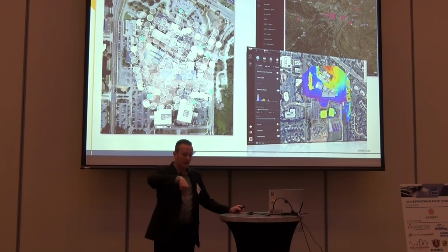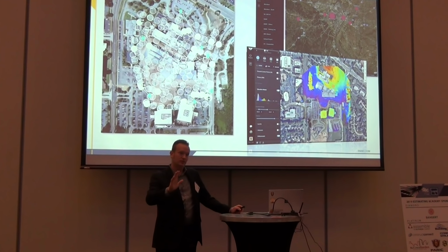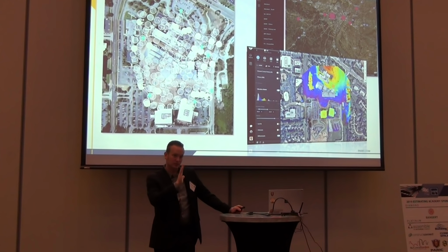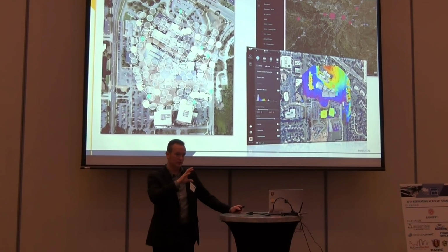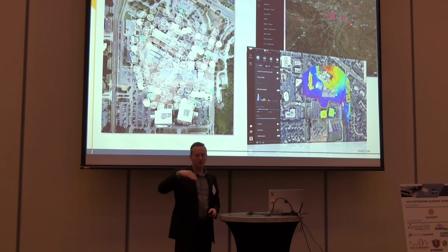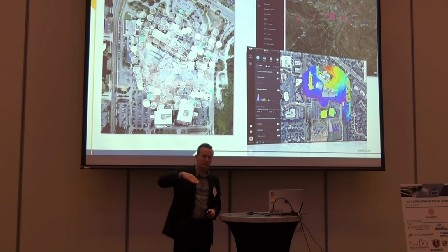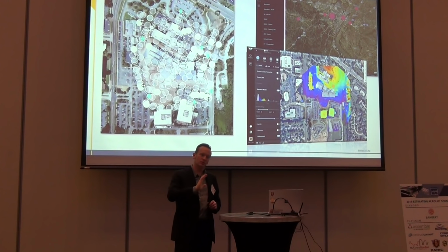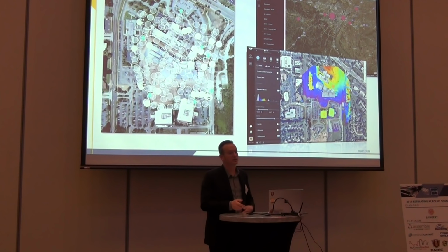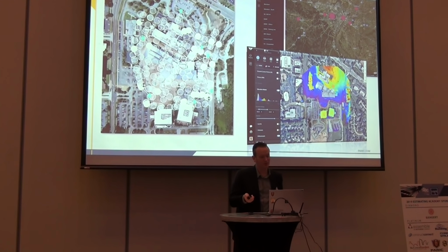If you want to know more about the face of a building, then you'll do what we call a crosshatch scan, but it's not oblique anymore. Depending on what you're trying to scan, it will look up at the building. In a crosshatch scan, you'll go in both directions and you'll tilt that camera up 15 degrees, 30 degrees, just enough so that it catches a little glimpse of the side of the building, so that when we try to stitch this stuff together, we get more of the three-dimensional aspects of the building itself, assuming there's a building.